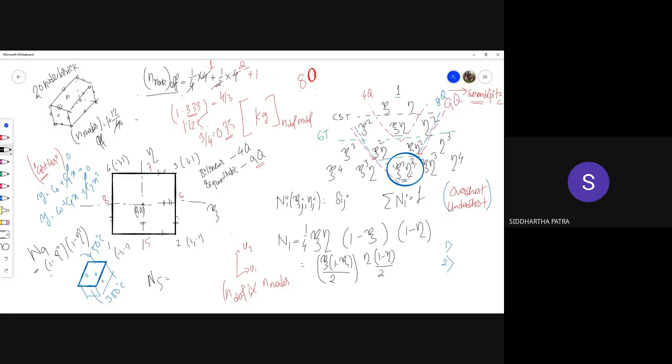So there would effectively be 4 nodes per element. That is 4 times the computational cost once you move from an 8-noded brick to a 20-noded serendipity element. Then if you include the face nodes, which none of the softwares do, there are 6 faces, and each face node would be shared with 2 elements. So you have 6 by 2. And then if you include the body center, that is not shared with anyone.